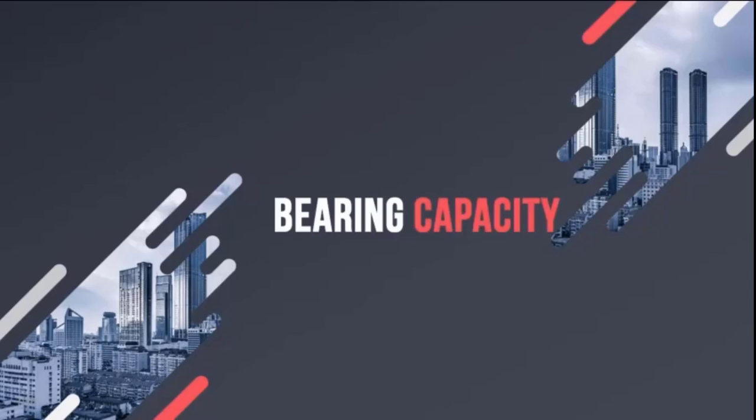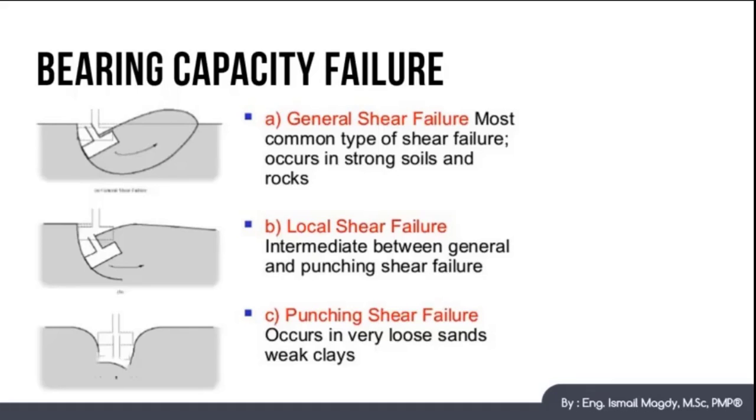In this video, we are going to talk about soil bearing capacity. In our last video, we mentioned that there are two main failure mechanisms for foundation, which are bearing capacity failure or excessive settlement. In this video, we are going to discuss more in detail the bearing capacity failure. There are three main modes of failure for bearing capacity. First one is general shear failure, which is the most common mode of failure and it occurs in strong soil.